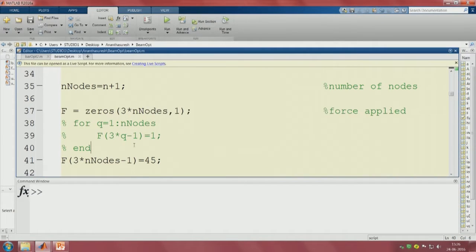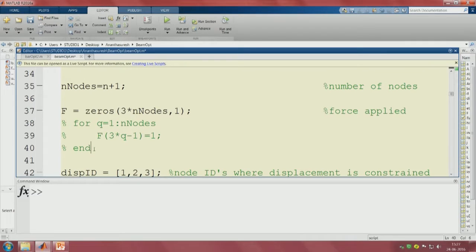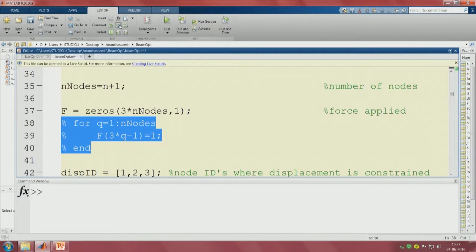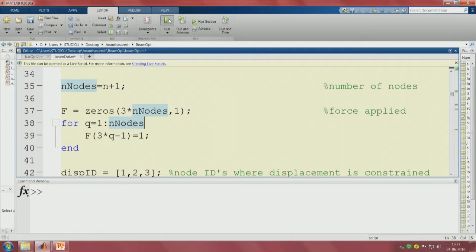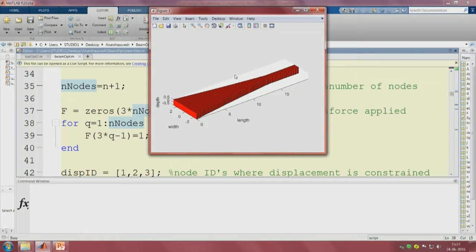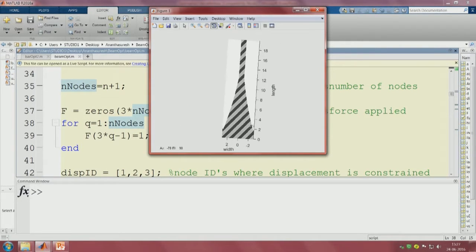All right. So, if you want again the uniform distributed load, you can have that. So, we can move back and remove, uncomment these things, run it again for cantilever, it will go back to that. There will be slight difference. Now, it is a little bit curved, whereas earlier, when you have only a transverse load at the free end of a cantilever, it becomes straight linear, but if you have a distributed load, it gets a little curved, and you can see this now, yeah, a little curved compared to the one that is there.